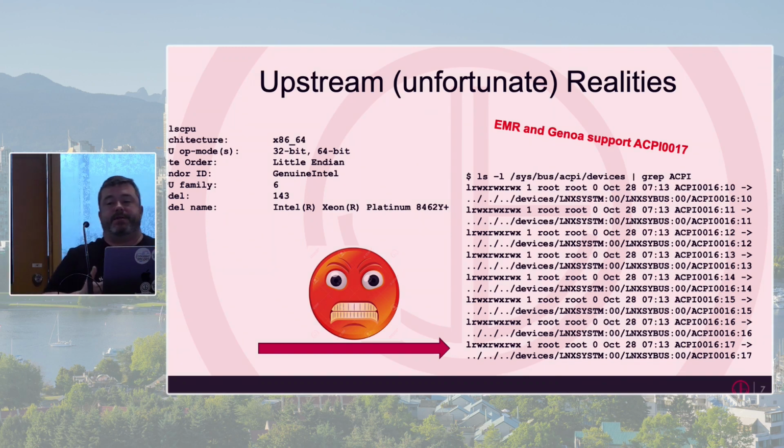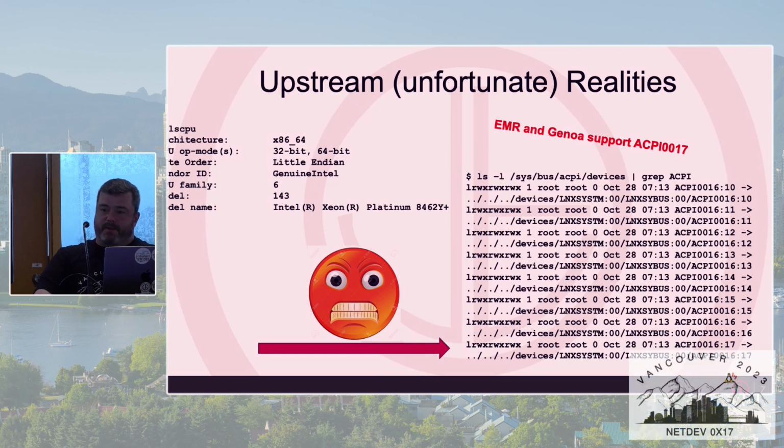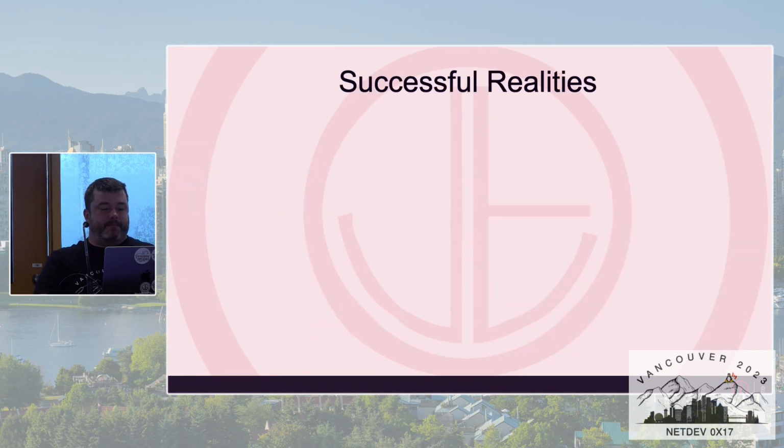If you look at AMD's Genoa, it says, hey, we support type 3 devices. We don't support type 2 devices. This is part of the 1.1-ish thing. But on Genoa, they actually do support .mem, type 3 properly. They do have this ACPI table. And we also got our hands on some Emerald Rapids, and lo and behold, this ACPI table magically showed up, and now Emerald Rapids supports type 3 devices. That's part of my life I'll never get back, but that's okay.